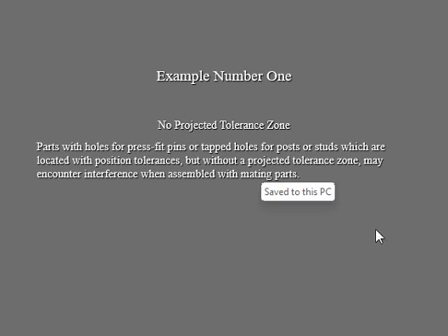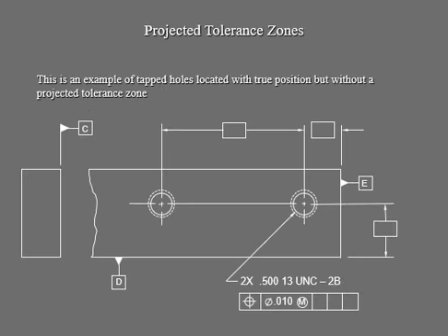And the projected tolerance zone is important because we don't want that interference in the assembled mating between these mating parts. Interferences, we call it noise, by the way, meaning there is something that doesn't belong there, and we don't want the intrusion of the other. We want this mating to be as functional as it should be. So we have to make sure all the tolerances are projected so that they fit well to each other.